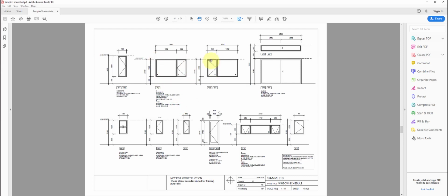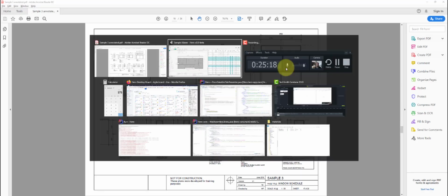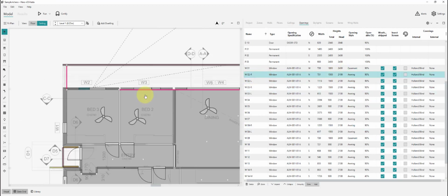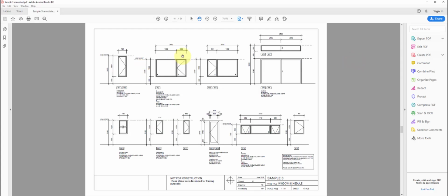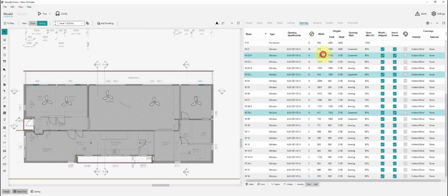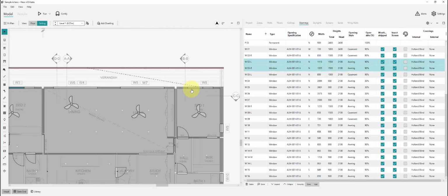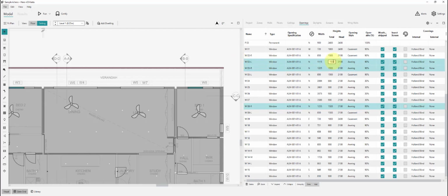We could go through all of the window 2, 3 and 8. They're all 1500 high windows, so we get their heights right. They're 1500 high with a 2100 roof height, 1500, 2100. And we can select our casement sections of those. They are 850 wide for window 2, 3 and 8. Our fixed sections of windows 2, 3 and 8 are 1800, 1800.